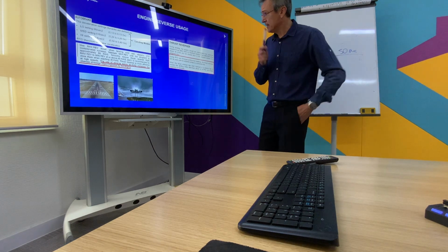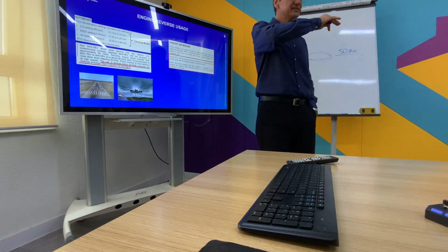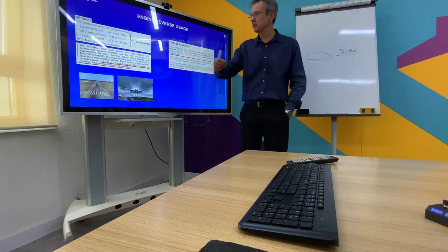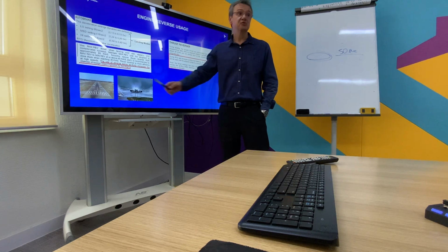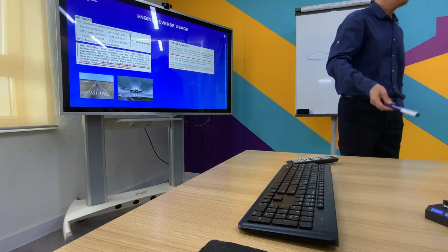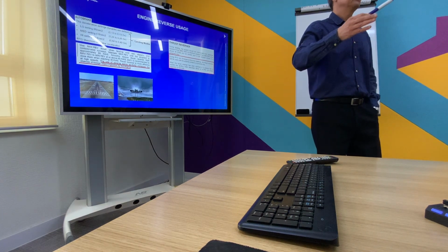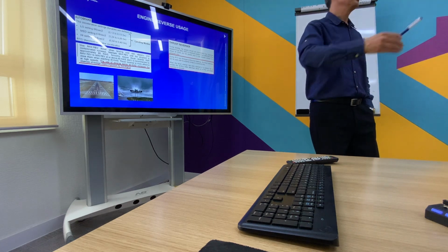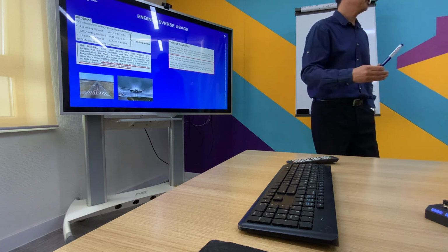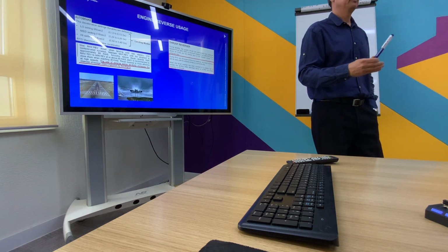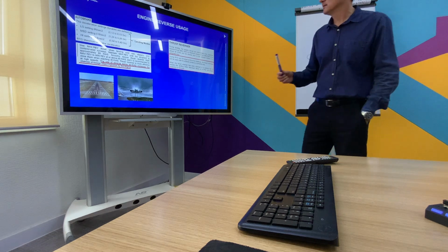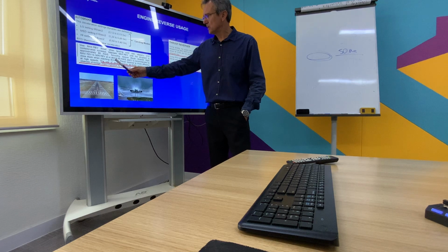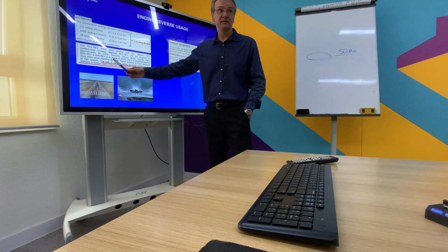Okay? And another, just to standardize your procedure as you are flying a mixed fleet from E1 and E2, and we do have a limitation for this reverse. You may use the reverse in case of reject takeoff, in case of any situation that the safety is a concern. You may use this reverse until a complete stop. You can use it. For safety, you can use it. Okay? But we have a limitation. You have to go to idle at 30 knots at least.